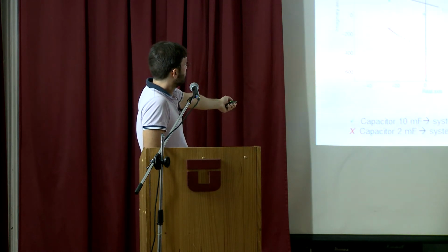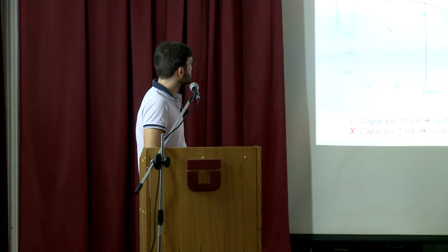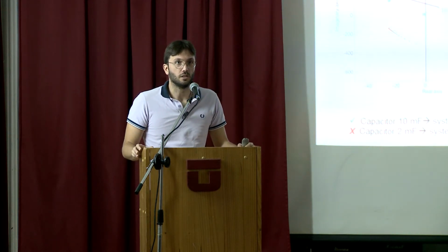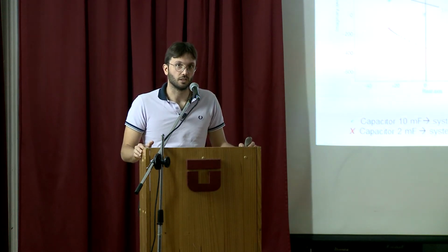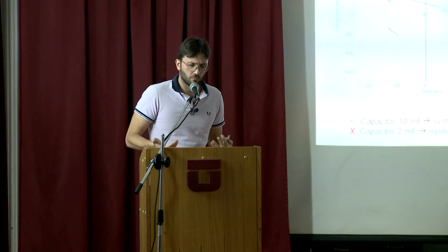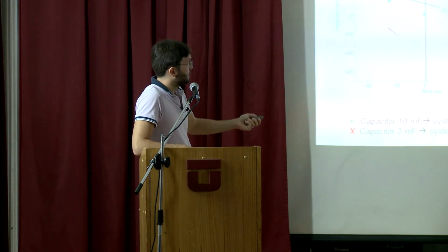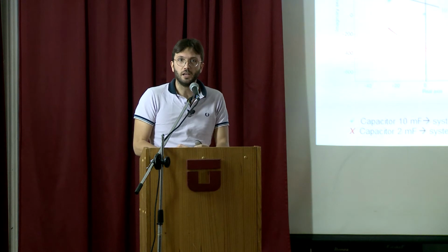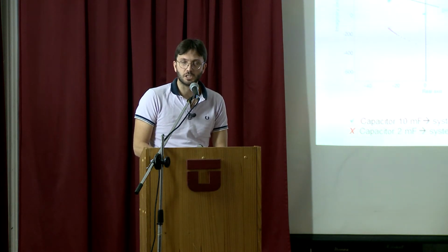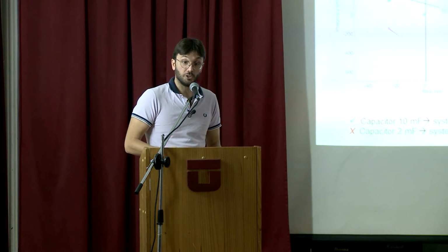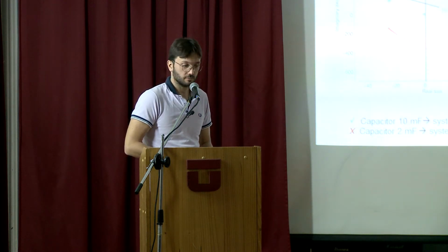But anyway, 10 millifarad of capacitance at 800 volt is actually nothing crazy if we are talking about megawatt power converter. So there is still margin. Consider that 10 Hertz is some reasonable value for a bandwidth of a commercial PLL. This can probably work in a real life situation.